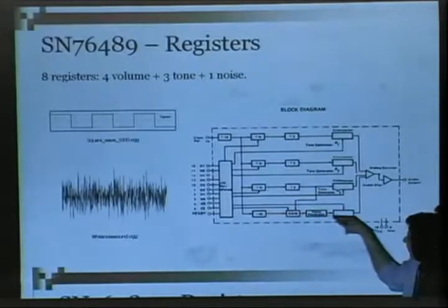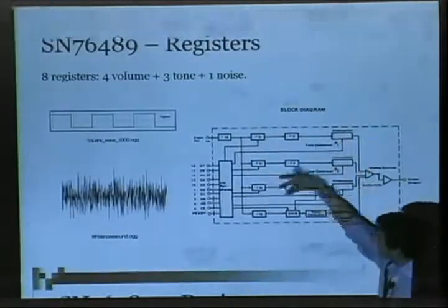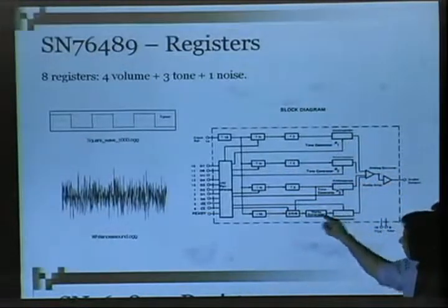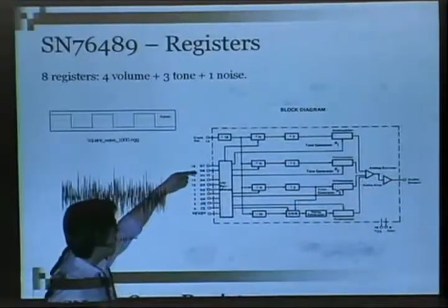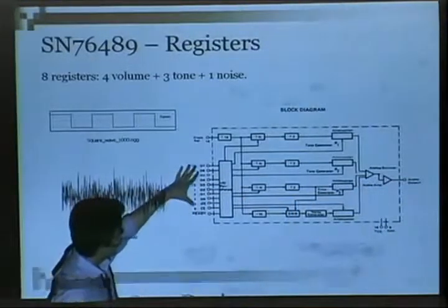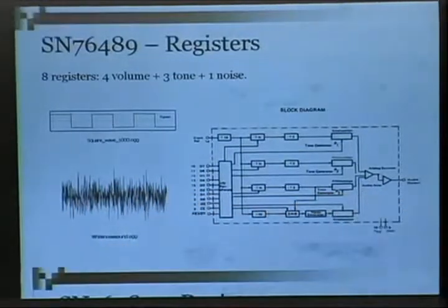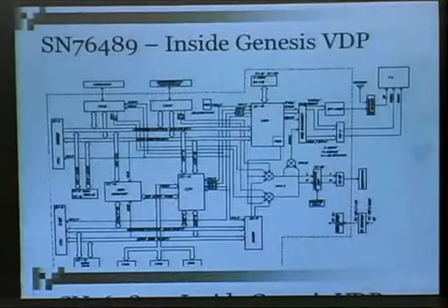See, these boxes represent a channel. This represents one of the tone channels. There's 3 square wave tone channels and a white noise generator. And to access those, you write binary on, off, in just 1 byte to access each of those channels. So depending on what you write to the chip, you can turn off channel 3 volume or set the frequency to a higher setting. I'll go into these registers later.